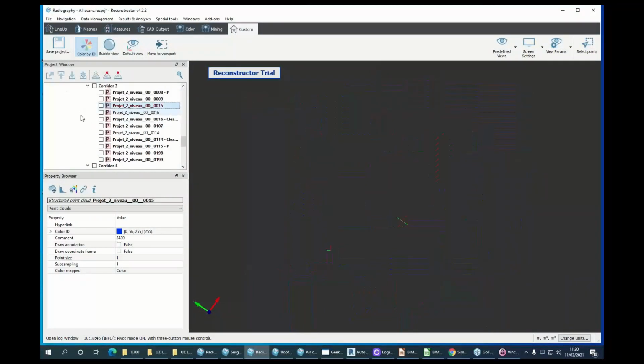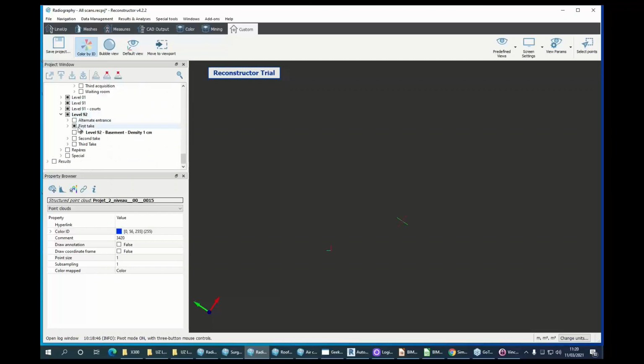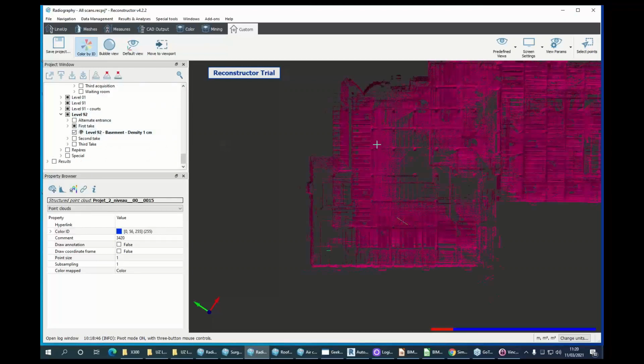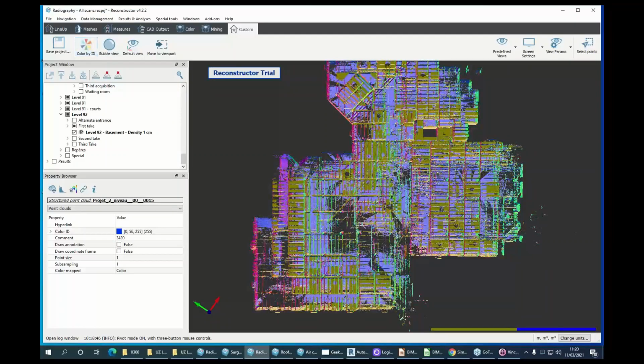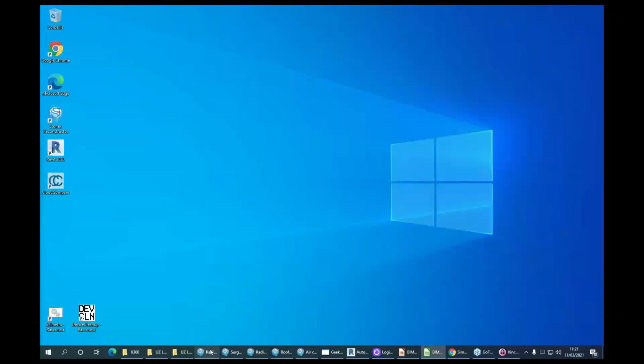If I take now the level 91, the basement, I have not prepared a view with all of the scans. We did a scan, but it depended on what we had on site. Some of these places have huge machinery, so we did what we could. Sometimes we did scans around the machinery, but given the range of the scanner, we know that one scan every 20 or 30 meters is good enough, and we put them in a checker pattern so that there's a good overlap between things. I'm not sure that helps a lot regarding the question.